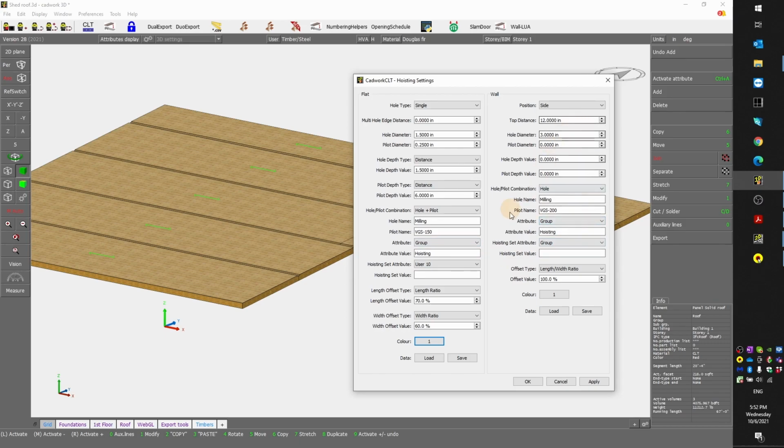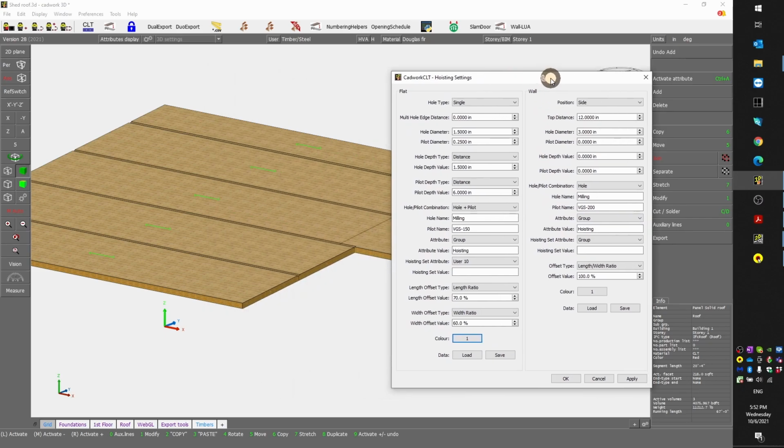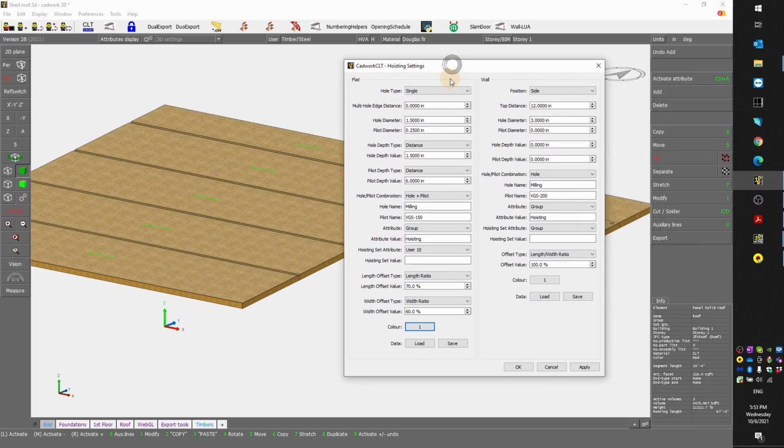Okay, well the rest, by the way, it's calculating the location of your hoisting, of the lifting points, and it takes into account the center of gravity. So that's important, and the shape of the panel in order to calculate that center of gravity. Now let's move to the flat panels, horizontal or at an angle, but not vertical again.